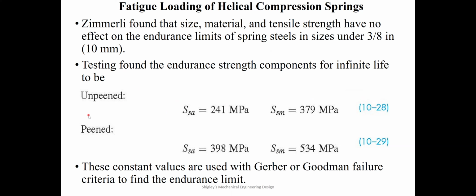And for the pinned springs, SSA equals 395, almost 400 megapascal, and the SSM equals 534 megapascal. So these numbers tell us these springs as pinned have higher alternating shear stress and mean shear stress.